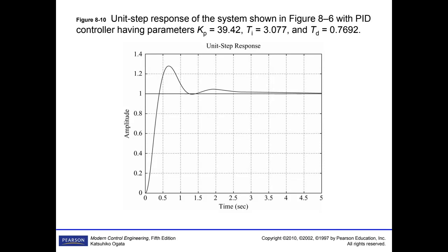The green one is telling you that there are two poles here as well, at the origin, and we are adding two zeros very near to those. So these two couples almost cancel each other.